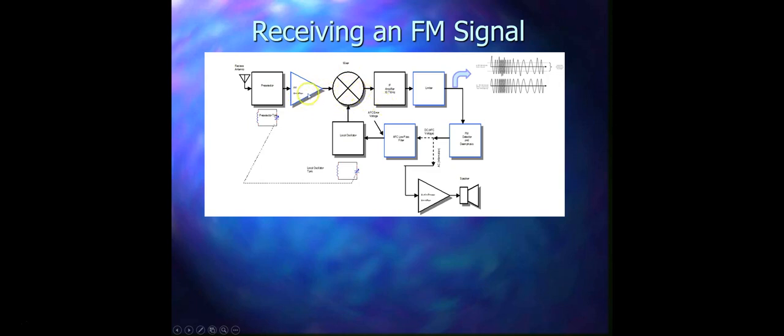If you talk about amplitude modulation, there it is not a problem, as the signal levels received at the antenna are in hundreds of microvolts. But in frequency modulation it is a problem. So that's why this RF amplifier provides sufficient gain for the incoming radio frequency signal to overcome any noise floor of the mixer.